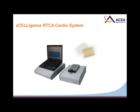So finally, just the last couple slides, I do want to mention this specialized cardio system, just because it's very unique, again, both the migration system and then this cardio system, they're very unique to our particular deployment of this impedance technology. Cardio system, what we did is we took the standard 96-well system and we simply reconfigured the electronics to increase the rate of data acquisition. So our normal system, if you really push it, you might be able to get a 5-second interval between different reads, but really more realistically, it's a minute. Typically. With this one, it's a millisecond time scale, so 12 milliseconds.